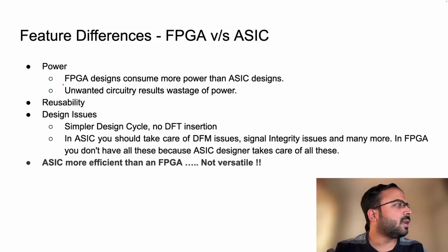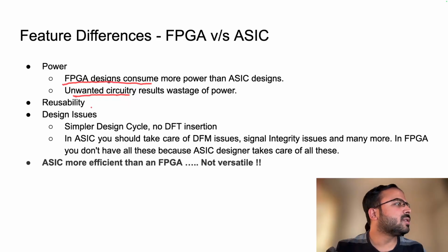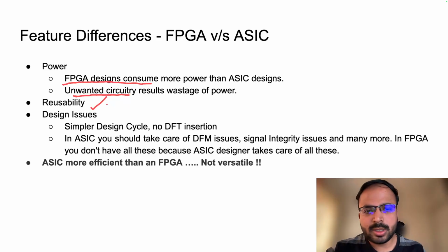So FPGA designs consume more power than ASIC designs, of course, because of more circuitry, some of which may not be used, but still it will be there. That is what it is saying: unwanted circuitry results in wastage of power. So ASICs are designed to be more power efficient than FPGAs. Reusability, of course, FPGA is more reusable.